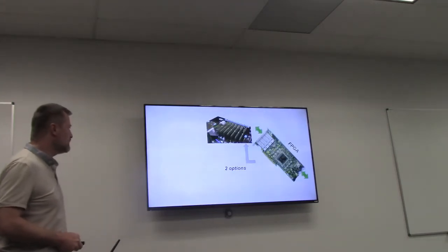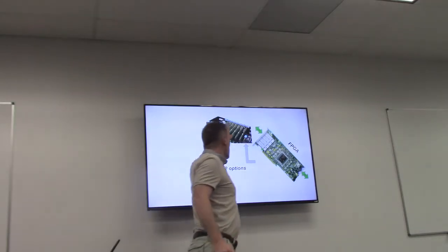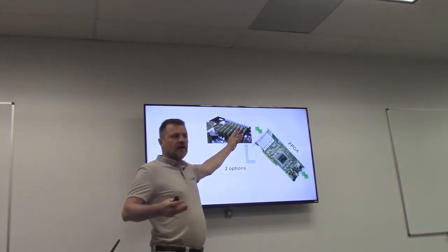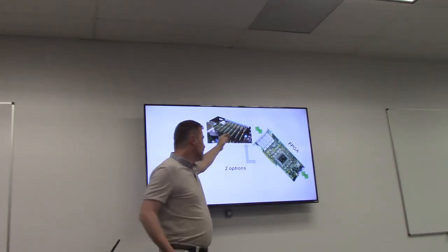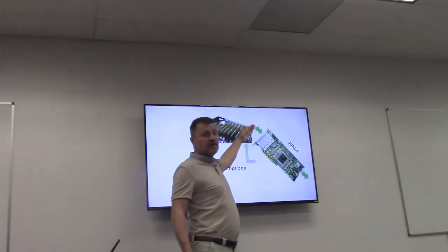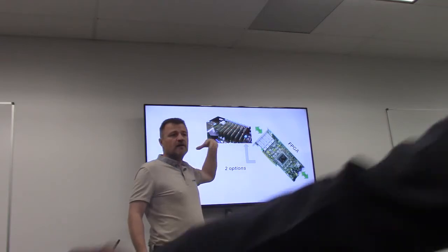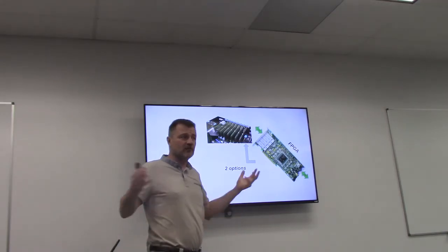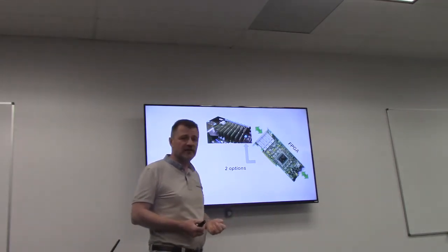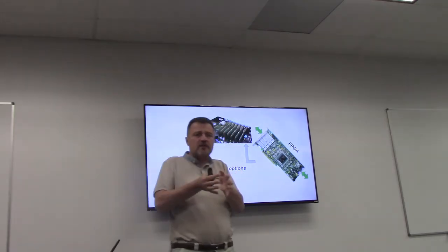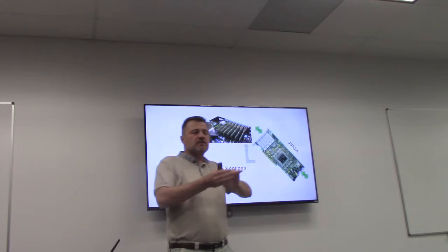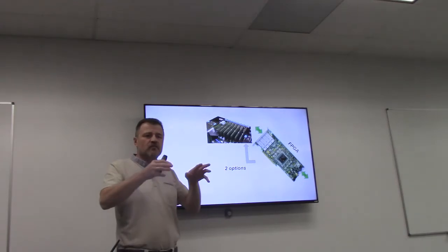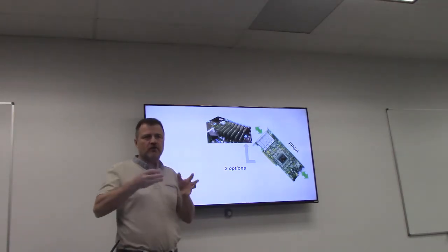Okay, I will not go very deep in detail, but see your host with several cards, okay? For CAPI technology 1 and 2, and the 3 is named OpenCAPI, is coming. For CAPI 1 and 2, we are using the same slots as the PCI, okay? CAPI 1 is using Gen 3 capability, and CAPI 2 is using Gen 4 capability, for those who know the speed of PCI Express. On this physical layer, we just use PCI Express for recognition of the card, but then we do not rely on PCI Express, we have our own connection.